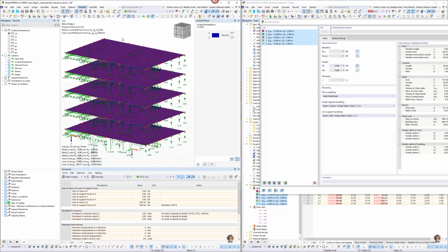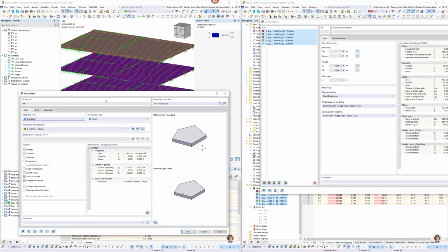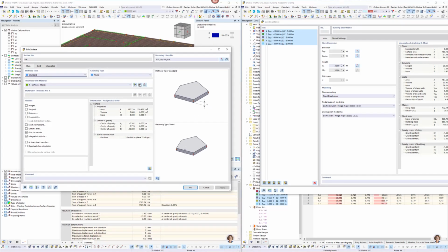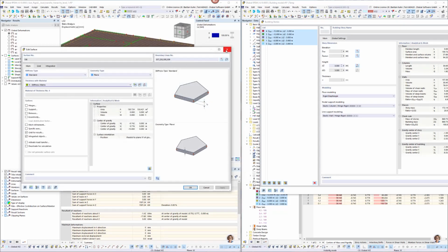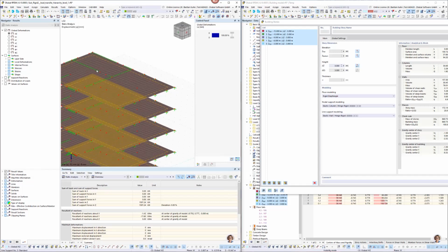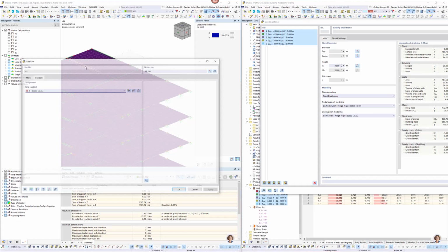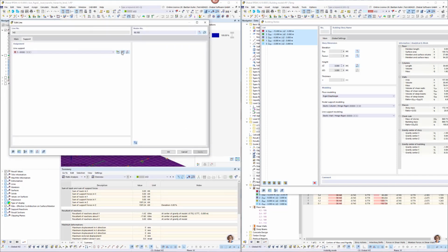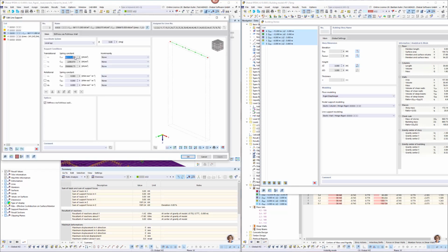Therefore, I created a different example. It's called submodel rigid 2. And there you see, first of all, okay, the surface, that's the same. It's the same stiffness, so very stiff in here. But the difference here is that the line supports and the nodal supports are now changed. Then they have a spring constant, linear, and this is defined now with this spring constant.